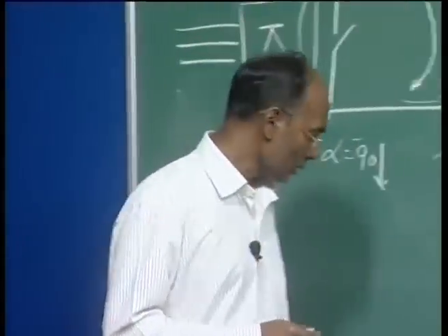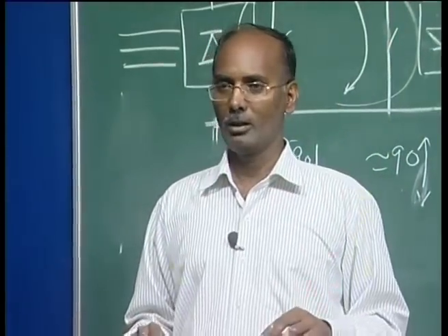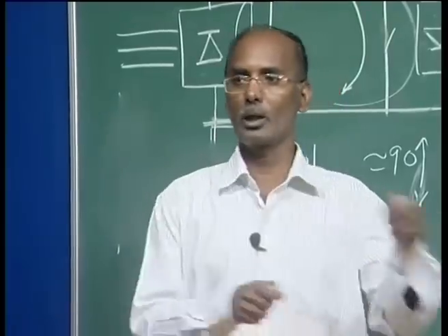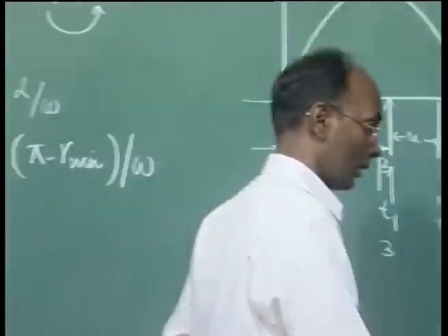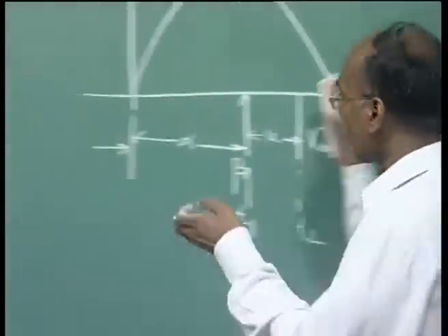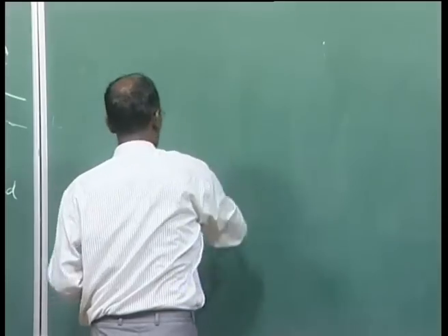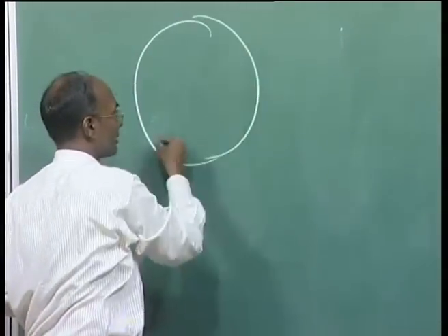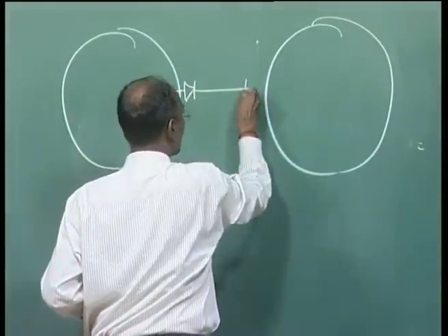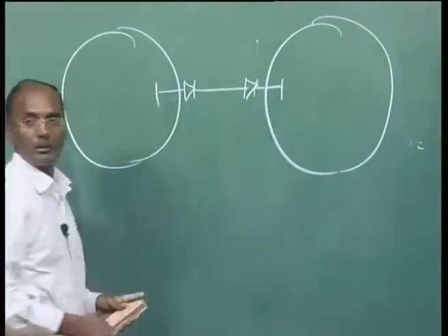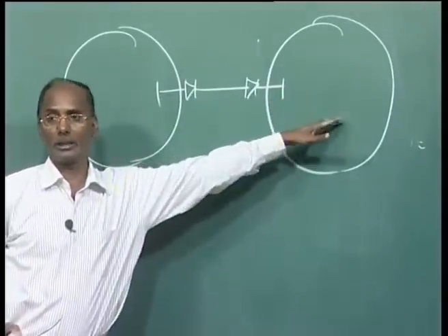But it is also possible if two areas are connected with the HVDC link. You can feed power from one area to another area to change the frequency of that area, and we can utilize this controller. But if it is a completely integrated system, then it is not possible. So, frequency control is only possible if there is an AC system here, another AC system or area there, and they are connected with the HVDC link. Then you can control the frequency of any area by power flowing into or taken from this area.